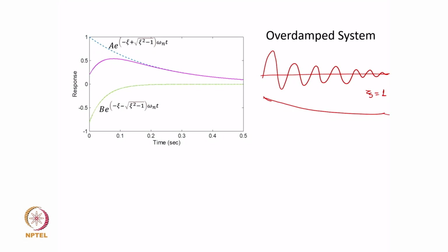But at the same time, you would also appreciate that if the door closes after too long a period of time, it loses its meaning, because one has to wait for a long time for the door to get closed. So, a target would be without oscillations if you want, or if you are willing to have a few oscillations like this, then you can have zeta close to 1, but less than 1, and so on.